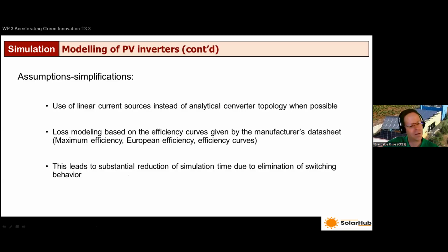It can increase the amount of power that the system can process, right? So it doesn't mean that a 400 volt three-phase system necessarily operates at lower power as opposed to the 700 V DC one, right?